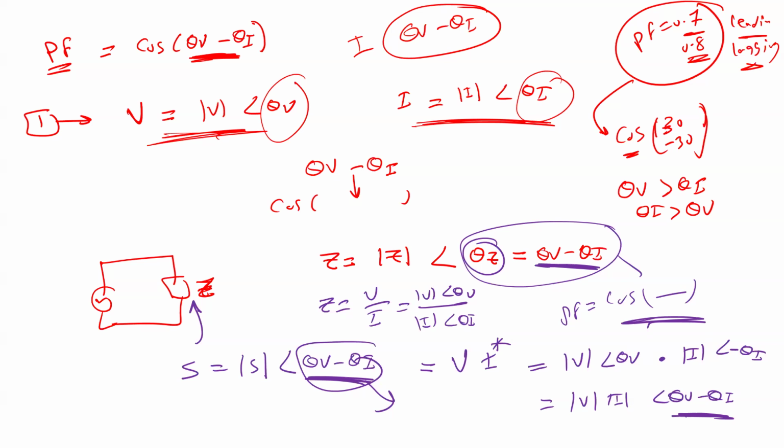Now I can get the angle, but you have to be careful, because the power factor is a cosine. It's always positive. So what you calculate from the cosine is always positive. That's why I told you leading or lagging. Whatever you get is going to be positive, or you need to add a negative. If it is leading, it has to be negative. Anyway, let's see how.